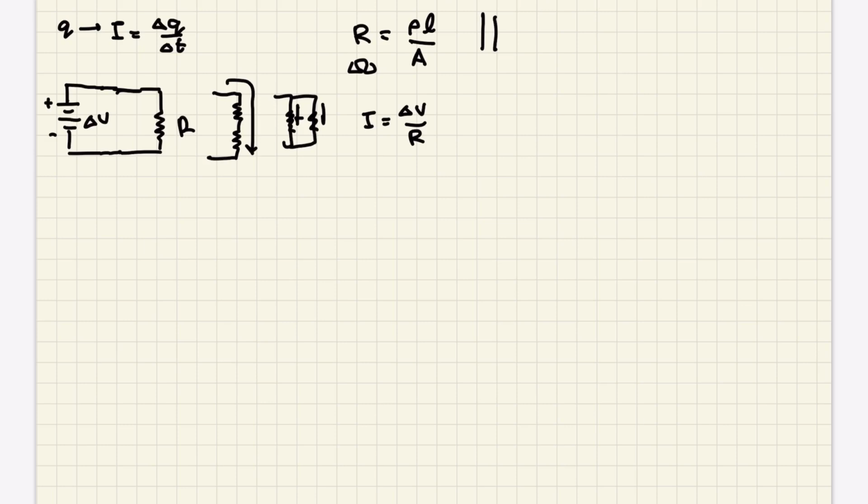Capacitors, we talked about what they do, but they also have this property, just like resistors, that's called capacitance. It's symbolized with C, measured in farads, again after another scientist, with the symbol F. Now, capacitance is the ability of charge to move within a capacitor with a given potential difference. And the equation for this one is C is equal to Q over delta V. And so it's the charge on each of those capacitor plates divided by the potential difference. And so if you have more potential difference across them, you can hold more charge.